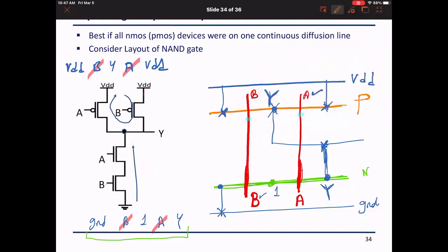If I predefine for you a path that visits B to A in the NMOS and a path in the PMOS that visits B to A in this order, and if I draw the poly in red on the two strips, I can follow the path and connect my nodes in the stick diagram. Is this step clear? Anybody has any questions about this step?